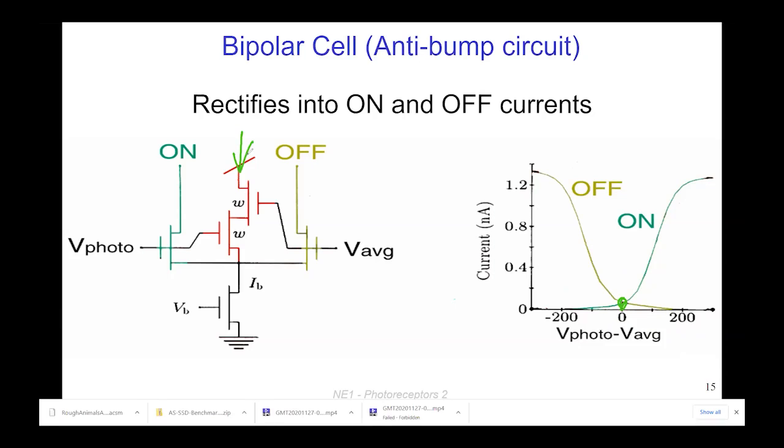And then finally, you've got to take those on and off currents and make spikes out of them. You know how to do that, right? You just tested the neuron circuit, I think. Was it last week? So all you need to do is hook up a neuron. You don't need any of this fancy DPI, SIDAPs, and all that kind of stuff. All you need is to take that current and send it straight into a spiking neuron. In fact, you don't even need a fancy neuron like this current feedback neuron. Just use an axon hillock circuit. It takes current and makes spikes.